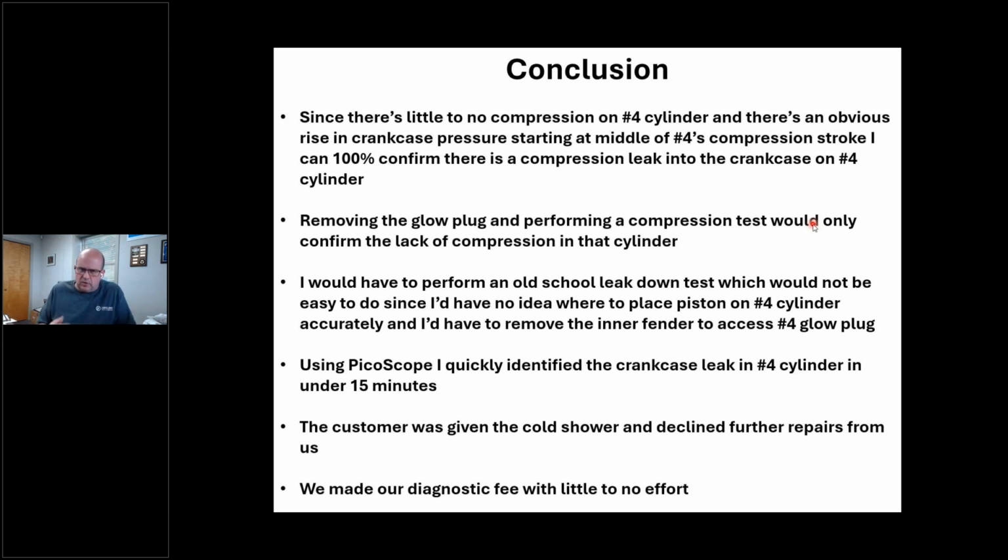We didn't take the glow plugs out. Okay, I'm not doing that. It's too much work. We could have done that, but guess what? If we would have done the old school compression test with a gauge, all that's going to confirm is I got no compression. It's not going to tell me where the leak is.